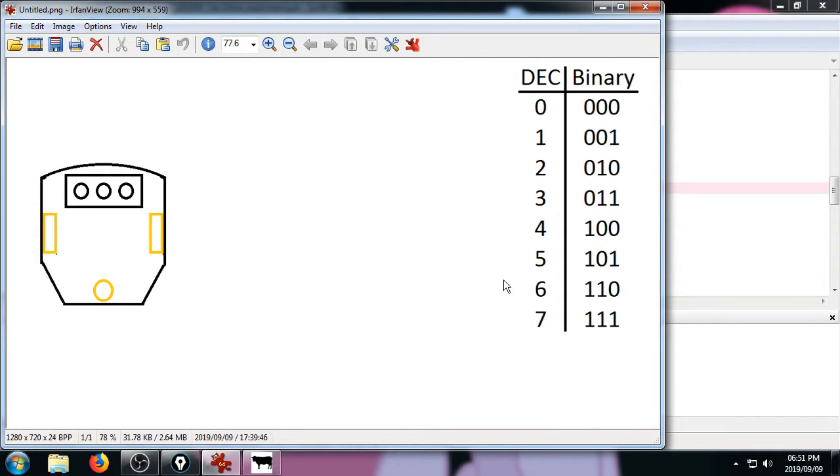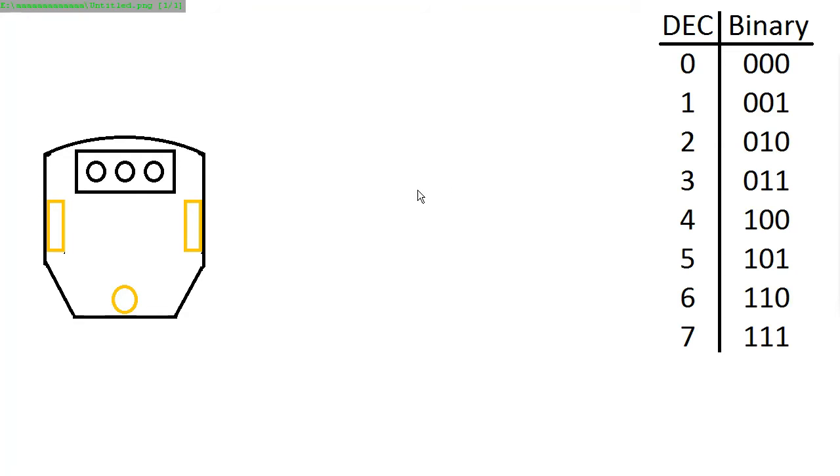Now, if we look at this table, we can think, what should the robot do? If it detects the line here, then it has to move the robot onto the line. So the way I did it was to reverse this motor and make this one forward, and then it basically pushes the robot onto the line. The same conversely. If it detects a line on this sensor, then it has to make this faster.